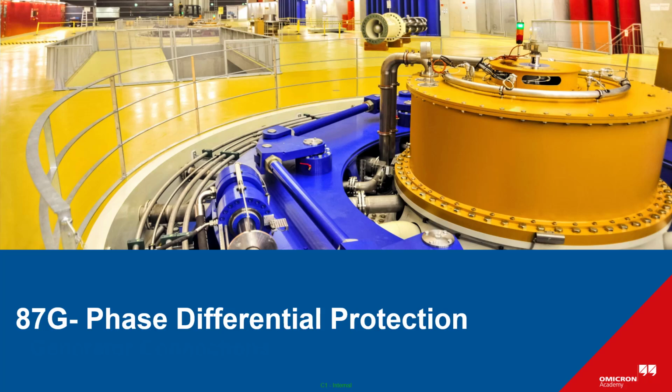Hello everyone, welcome. In this video we will explore the generator differential protection, or 87G, which protects the generator from internal faults. It works by comparing currents at both ends of the generator to detect any differences. The protection is designed to be sensitive enough to catch internal faults while remaining secure and restrained against external faults from CT errors or through currents. We will also look at key concepts like the bias current, the minimum differential current, and the slope settings that ensure reliable operation. So let us dive in.